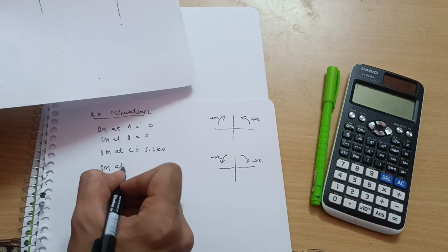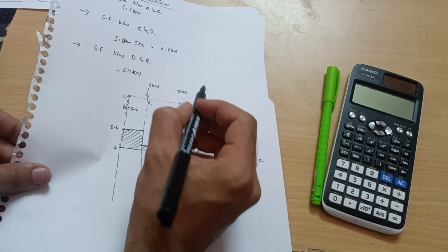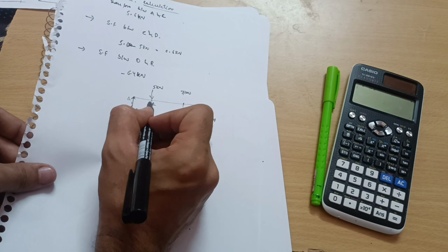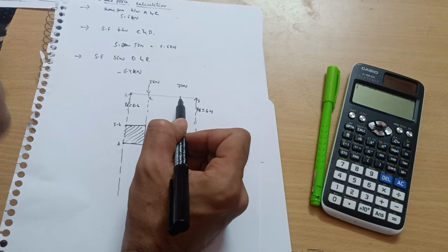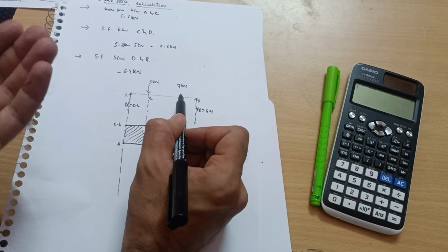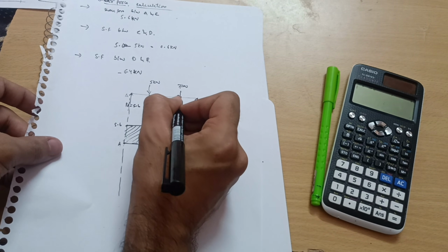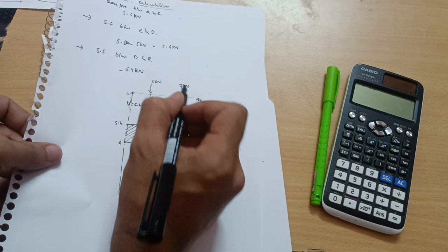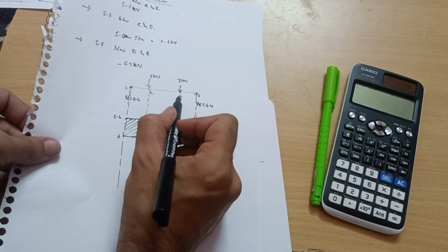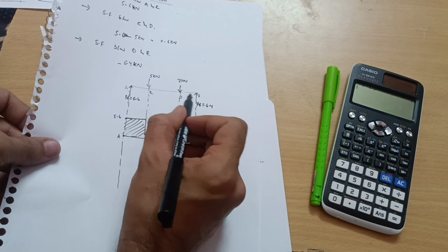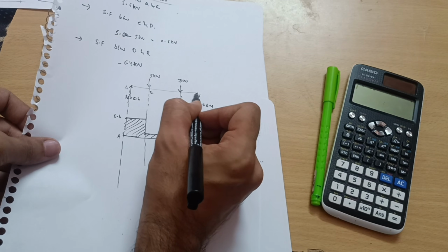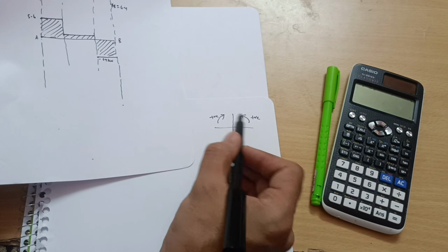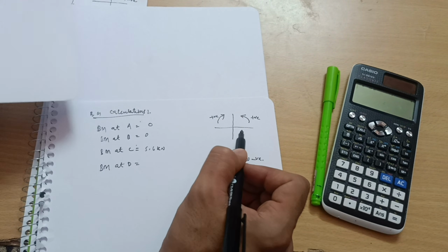Now bending moment at D. See here, for bending moment at D, I will definitely go for the right hand section, only one force is there. If I take the left, I have to take two forces. Where you are calculating the bending moment, that force you should exclude. You should remember this one. Wherever you are applying moment, at that point, whatever force is there, you have to neglect that one. So I have to take only the right hand side force, only one force is on the right hand side. It is upwards, meaning with respect to D, it is anti-clockwise. If it is on the right hand section and anti-clockwise, you have to take that one also as positive, as per the rule of the bending moment.